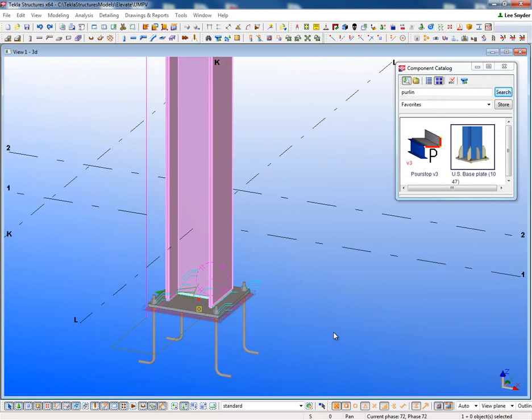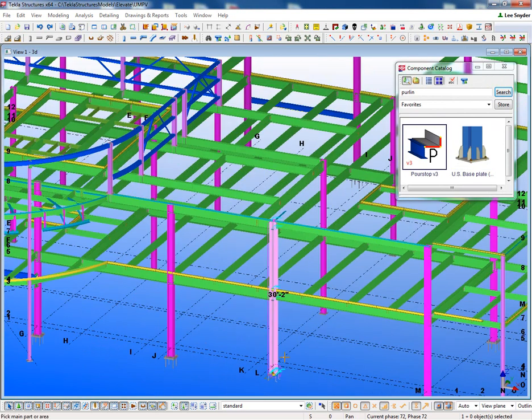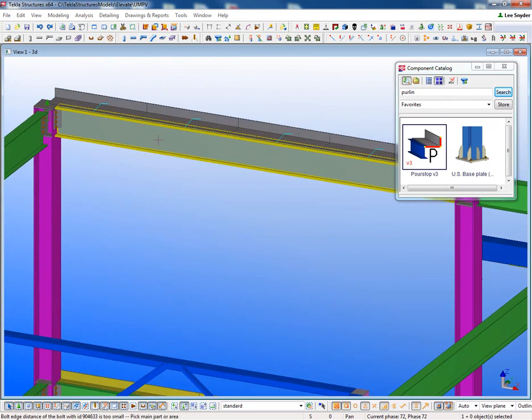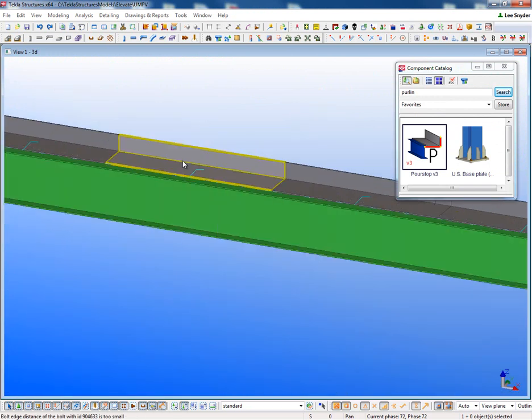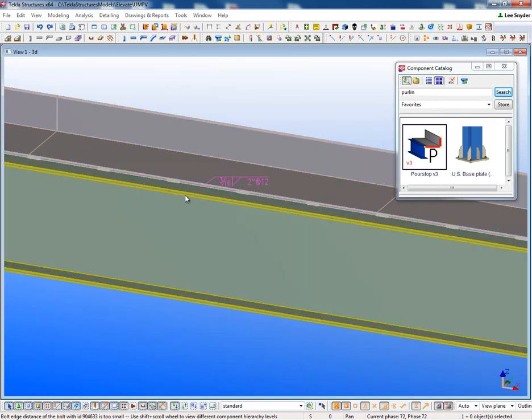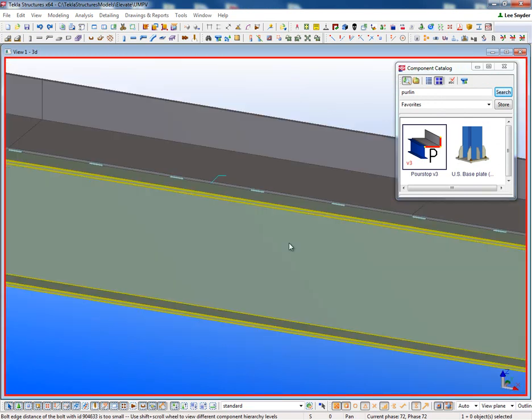One other quick example to show some of the other options and availability is to use this pour stop component, for example, which puts in a bunch of pour stop or bent plate. You can see this stitch weld here where it's calling in 3/16 fillet, 2 at 12, and then you can see the weld solids placed throughout there.